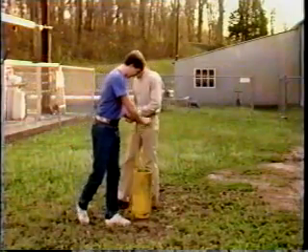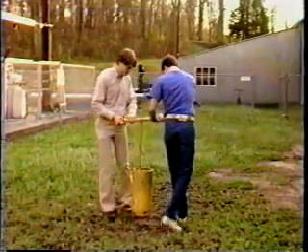One of the common problems is a great deal of tuberculation or scale inside the pipes. This tends to reduce the carrying capacity of the line. This type of problem usually shows up fairly gradually. If the loss of flow from the hydrant occurs rather abruptly in time, it's probably due to someone having left the valve closed or partially closed in the system.